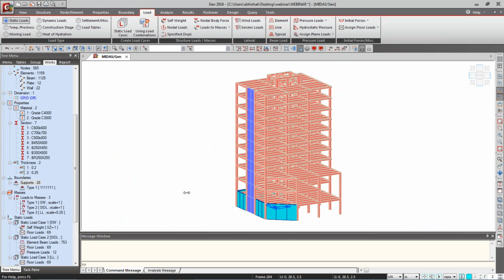So okay, you were asking about one more option: what is the 0 and the 90 degree. 90 degree and 0 means, if you want the one way direction to be horizontal, you have to say angle is 0. If you want to distribute my one way loading vertically, you have to say 90 degree.